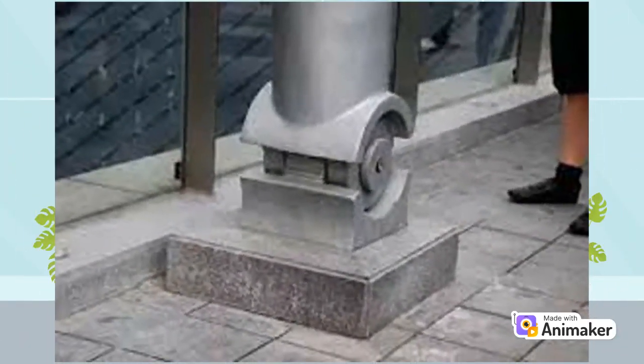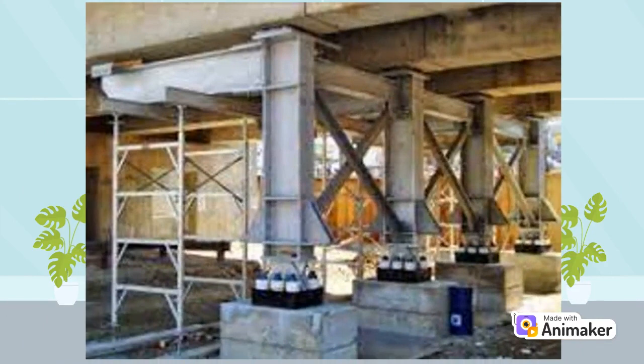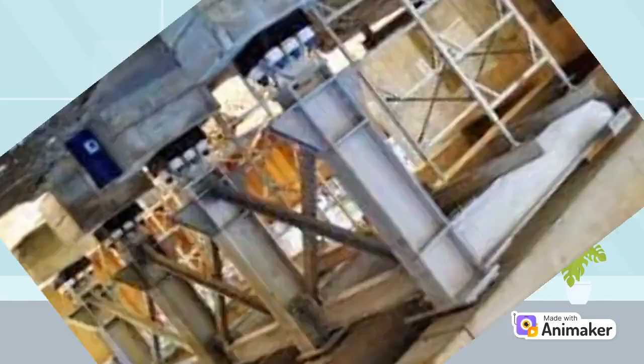The reason for providing roller support at one end is to allow contraction or expansion of the bridge deck with respect to temperature differences in the atmosphere. If roller support is not provided, then it will cause severe damage to the banks of the bridge. But this horizontal force should be resisted by at least one support to provide stability, so roller support should be provided at one end only, not at both ends.